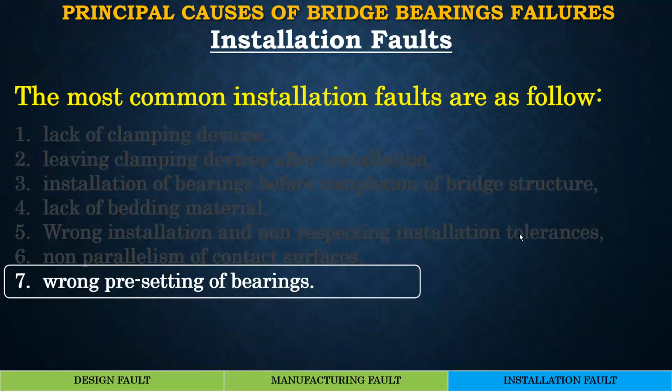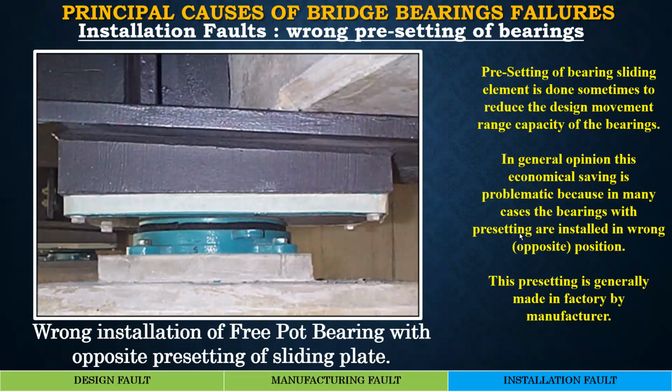Wrong presetting of bearings. Let me tell you, presetting of the sliding element of a bearing used to be a practice. I think it is still a practice. Some people still do it, and it is done to reduce the design movement and the range of capacity of the bearings. Basically, the top plate of the bearing should be large enough to accommodate the translations due to creep, shrinkage, temperature, etc.